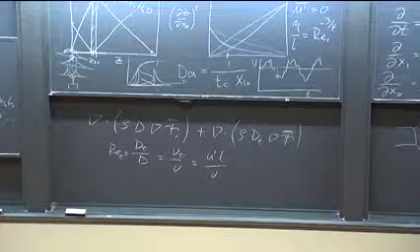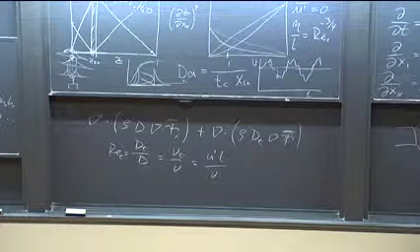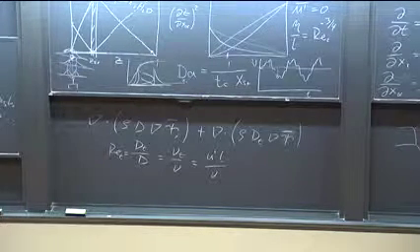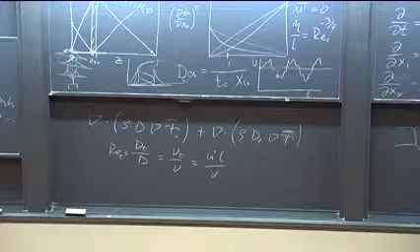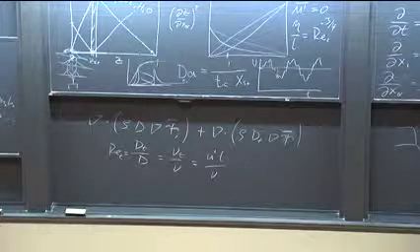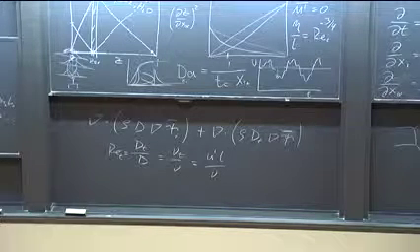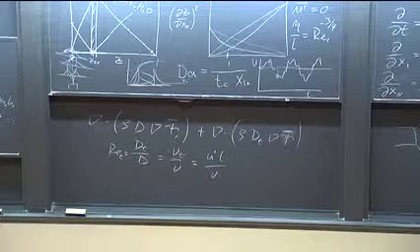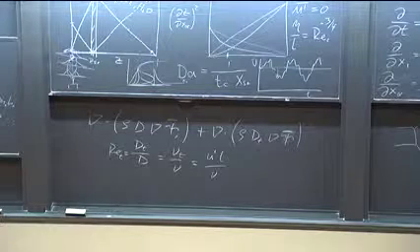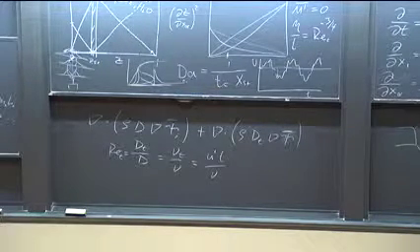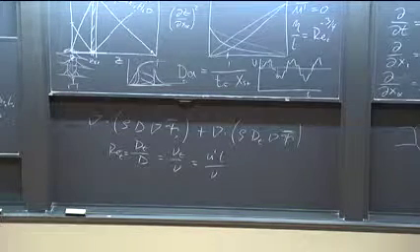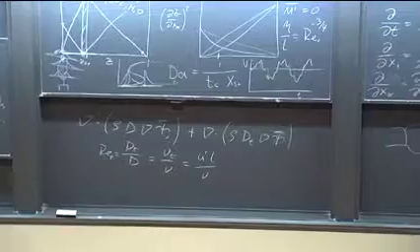Because we know this is a scalar flux, just like the molecular flux, the turbulent flux has the same form in the equation. We want to make this look similar to the molecular flux, and so we introduce the assumption that it is proportional to the gradient times a transport coefficient. So this is like Fick's law, just with a turbulent transport coefficient, and that gives you the same term as I showed earlier. And then we can have a model for this.